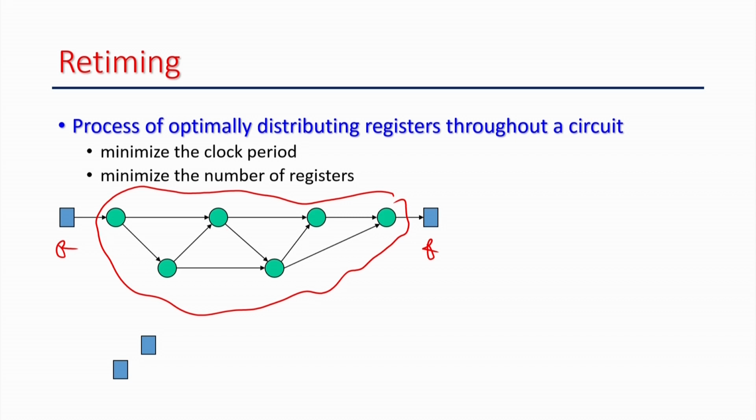Okay. So, what is happening here, you can see that the maximum length here is 1, 2, 3, 4, 5. So, the maximum combinational length is this, 5. So, the number of gates in a path is 5, right. And whatever delay you are going to get is the summation of the delays of this combinational unit. All the AND gates and OR gates have some delay associated with them. It needs some processing time, that is the combinational delay of that particular node. So, the maximum clock period will be determined by this 5 units of gate delay.